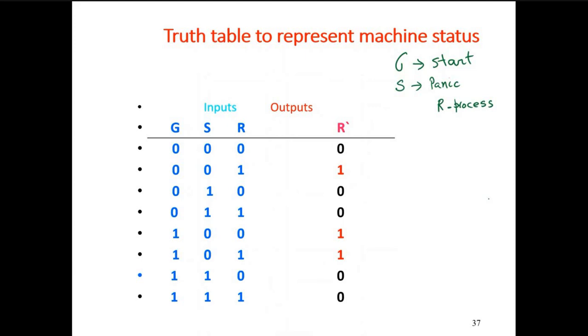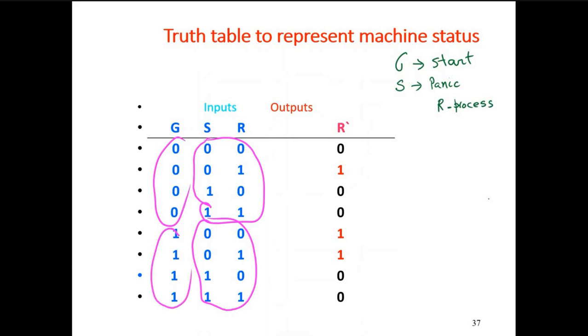Again, an 8-row truth table. Look at this. Constructing the truth table is no different from the previous section. But this is different. I, as the designer, decided that for the possible combinations R prime will be true in row 2, row 5, and row 6. Nothing else. So in this case, we have 3 ones and 5 zeros, which is going to be more compact. Writing an equation for the 3 ones versus the 5 zeros is going to be easier.